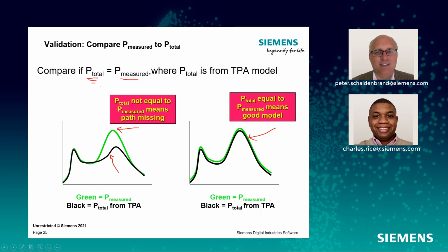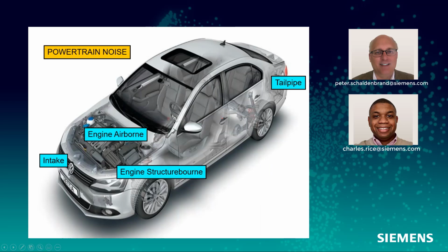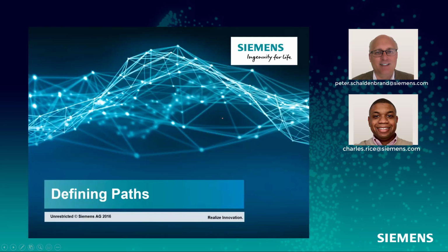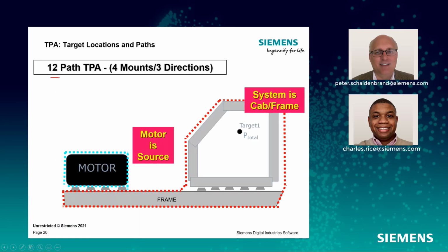Again, this is a technique that could work with simulation models, so it may not even be measurements that you do. You just need a set of FRFs and a set of forces. And you can even do what we would call hybrid models. And nowadays, hybrid means both gas and electric motors. Hybrid in this case would mean I could use a combination of a simulation model with test data, right? Because I don't care where the FRF comes from, et cetera. All right, so let's look at this a little bit more, how these paths work.